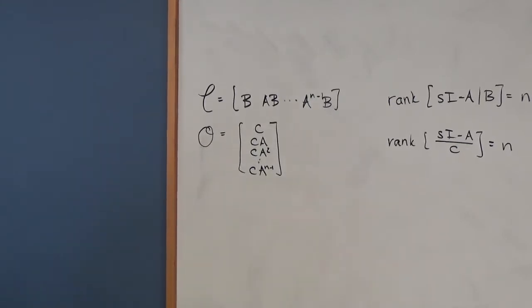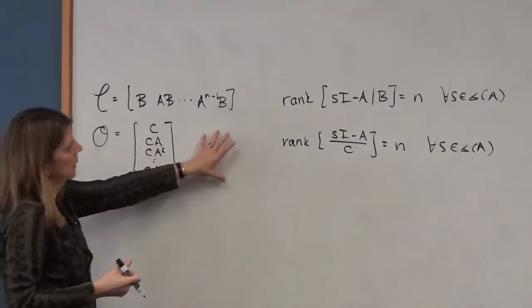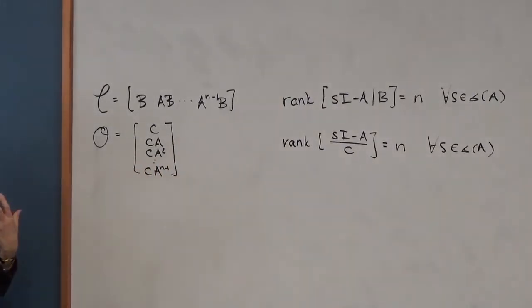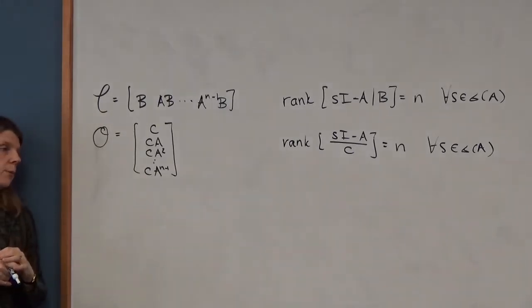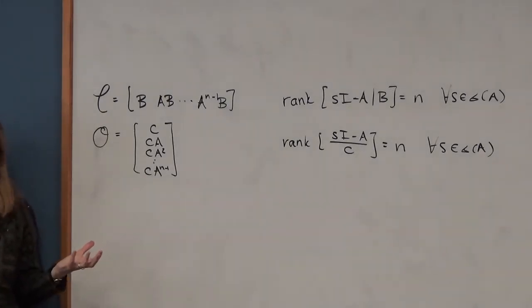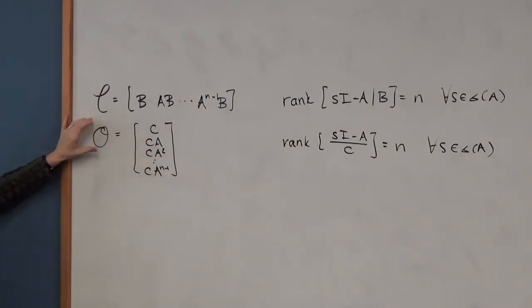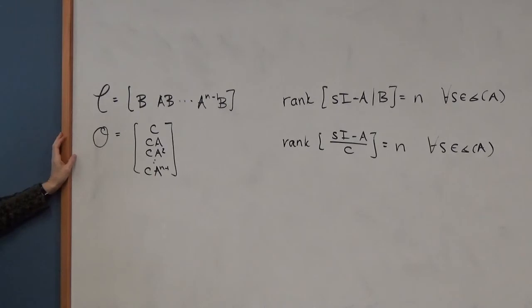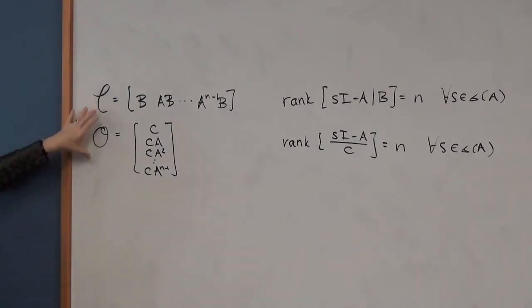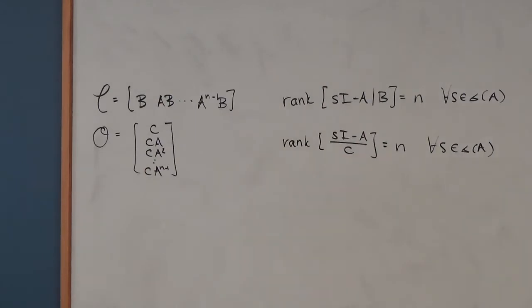They're typically easy to compute tests, and so you understand the equivalence. The theorems that you have to prove for observability in the homework are really about understanding the equivalence between the observability Gramian that we developed and proved for linear time varying systems, and thus holds for linear time invariant systems, and these simpler tests of the rank of these matrices. These are simpler than looking at the rank of the corresponding Gramians for linear time invariant systems.